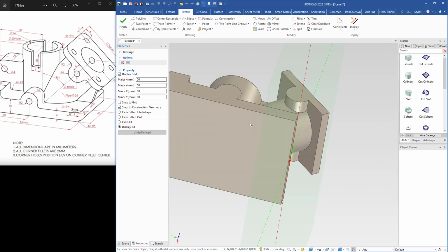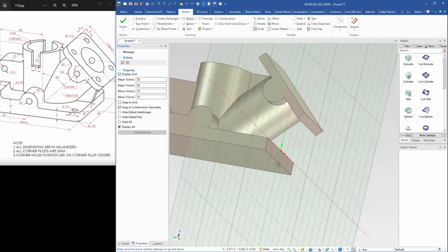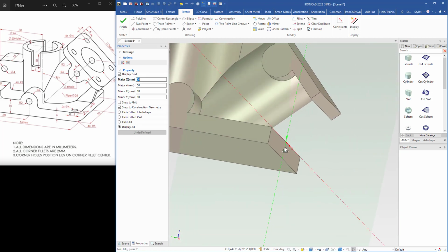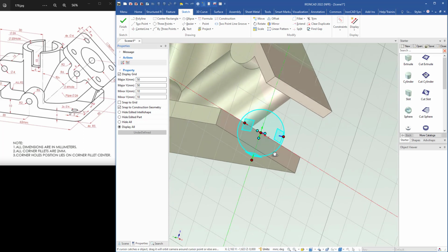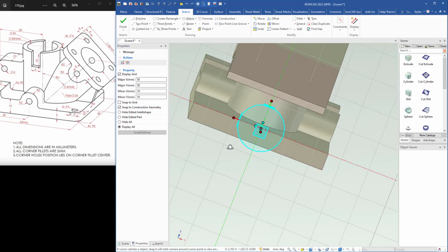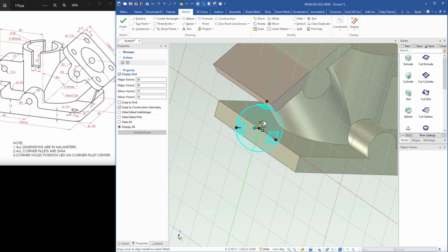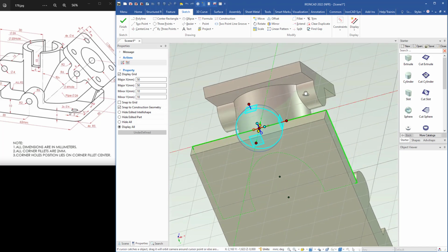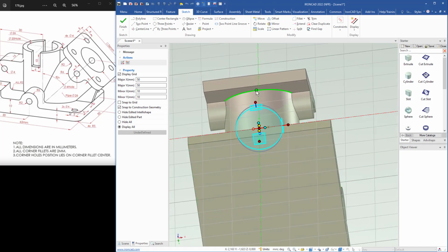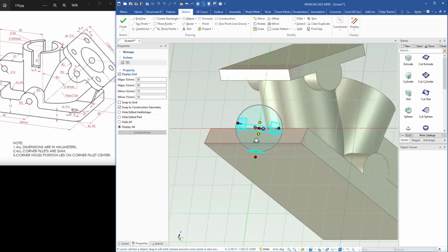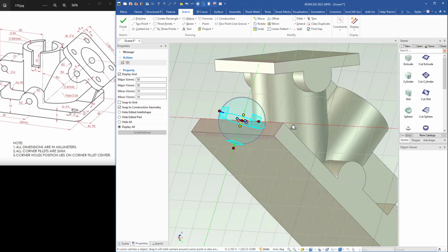I have to add a line, but first I have to rotate this grid a little bit. So I turn on the triad and I make sure that I see this handle on this side. I right click the handle, choose to point, and I will select this node up here so that the grid is pointing to that node.